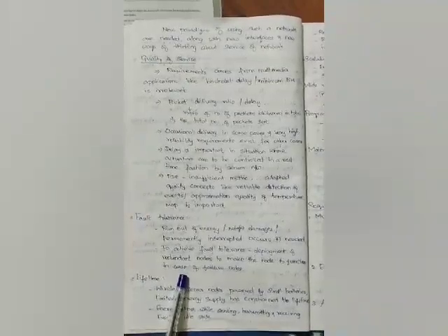The next one is fault tolerance. Mostly problems like nodes running out of energy, and in some cases there might be damages or permanent interruptions. In such cases, fault tolerance is also needed. To achieve fault tolerance, redundant routes are deployed so that the node can function in case of failures.